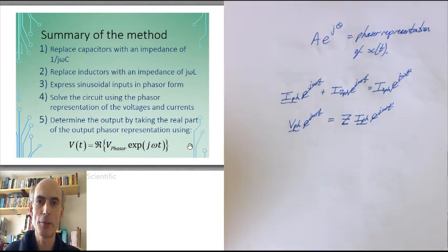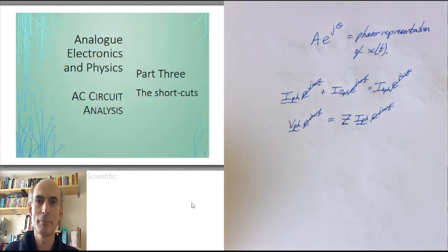But note, this technique only works for linear circuits because we are in effect using superposition. And it only works if all of your sources are going at exactly the same frequency. Next time, we'll have a look at an example of this now simplified technique.